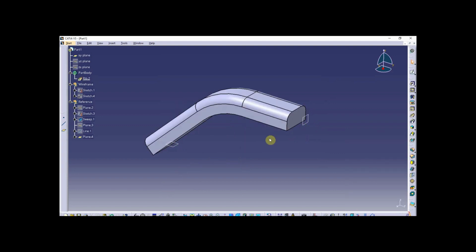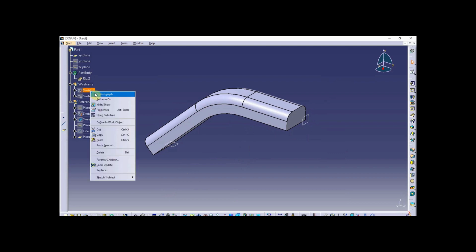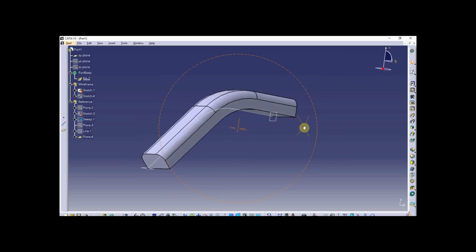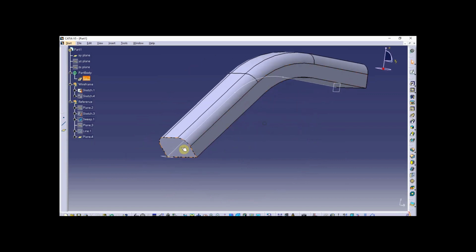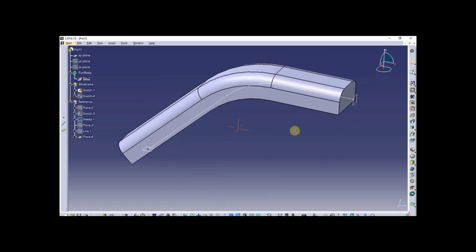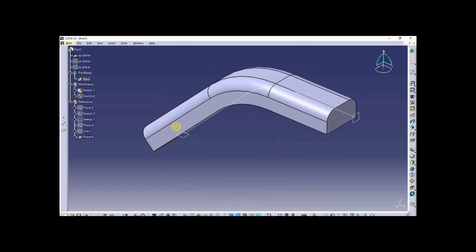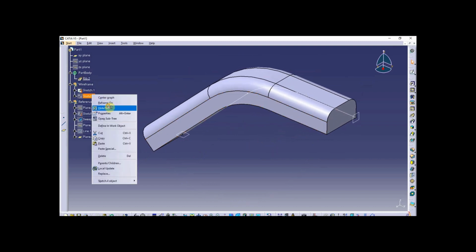And you can see that whenever I preview, and I'm going to unhide the center curve, but it keeps that normal in this case. So you can see the end profile here. It keeps it normal. And it's keeping it normal because the sketch is starting out normal. So instead of normal, I should probably say 90 degrees. So it's keeping it 90 degrees. But let me show you how that can change. So I'll turn my profile back on.